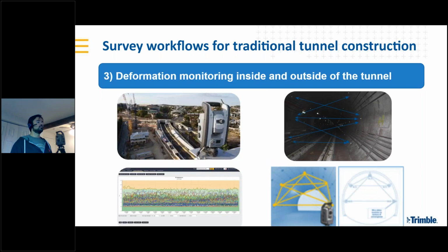And another key part of, well, really any tunnel is deformation monitoring. So this happens both in and outside the tunnel. So outside the tunnel, this is about understanding and alarming and reporting to the necessary stakeholders all of the key infrastructure that is around and above the tunnel. So this could be as simple as understanding, is a building moving while the tunnel is being bored underneath.